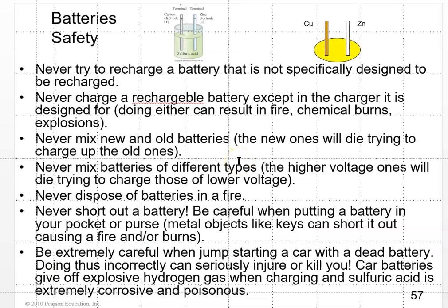Batteries also have their own set of rules for safety. Never try to recharge a battery that's not specifically designed to be recharged. Never recharge a chargeable battery except in the charger it's designed for. Doing either of these can result in fire, chemical burns, and explosions. Never mix new and old batteries. The new ones will die trying to charge up the old ones. You're not saving anything. Never mix batteries of different types. The higher voltage ones will die trying to charge those of lower voltage.